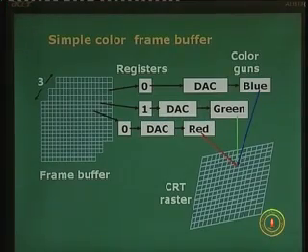You can visualize red, green and blue, and all the beams from all the 3 guns are simultaneously fired onto 1 pixel point, and this pixel should also have 3 dots respectively for R, G and B, and they will receive the corresponding intensities of the guns and illuminate a pixel which will appear as color. The CRT raster will have the same resolution as the frame buffer, but each pixel has 3 dots. That is the significant difference.